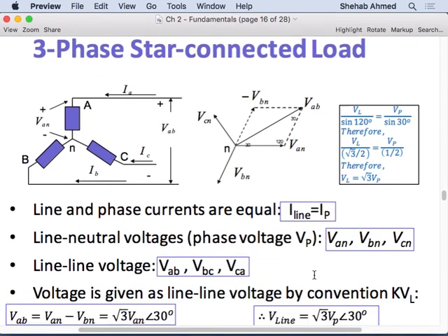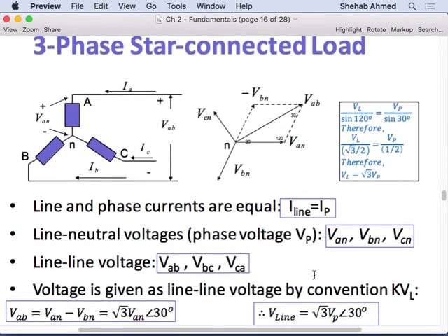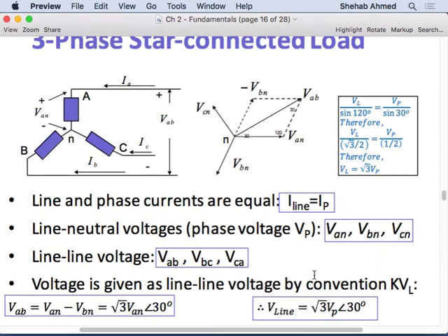But the main goal here is the beauty of being able to do single-phase equivalent circuits. Anytime we have a balanced system, whether it's positive sequence or negative sequence, any 3-phase balanced system with voltages and currents 120 degrees apart, then we can do single-phase equivalent circuits. I would like to do that because I don't want to play with 3-phase systems. If I have to, I will connect the 3-phase voltage sources here, solve too many loop equations, have too many unknowns, and I don't like that.